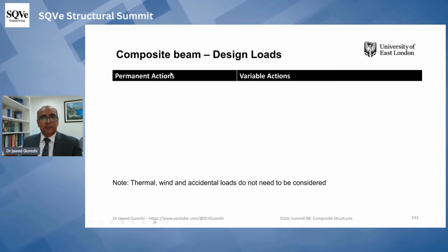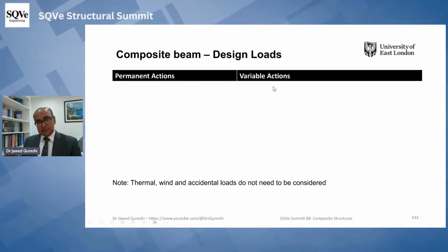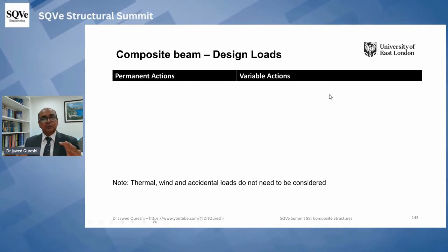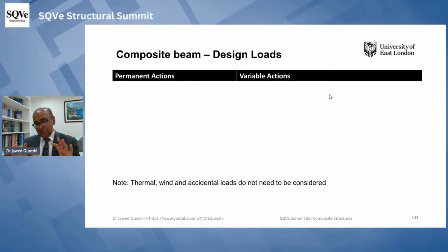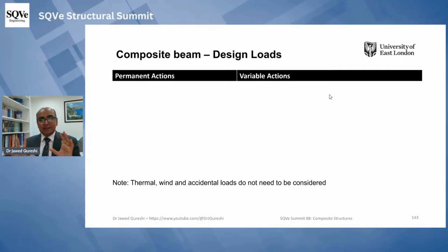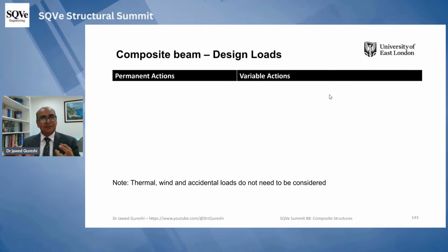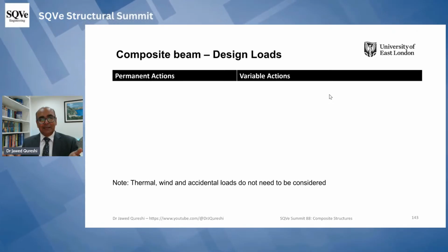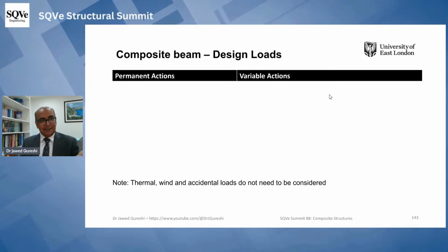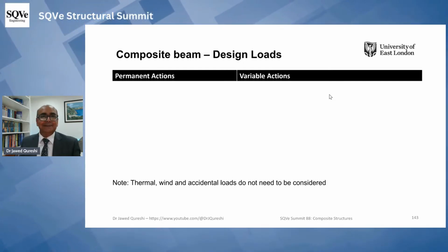Now, what are permanent actions and variable actions? I'm sure these terms might be new to you, but this is another fancy way of Europeans to make things complicated because we want to impress people. Permanent actions means dead loads. Variable actions means live loads. So for simplicity, I will call them dead and live rather than permanent and variable.